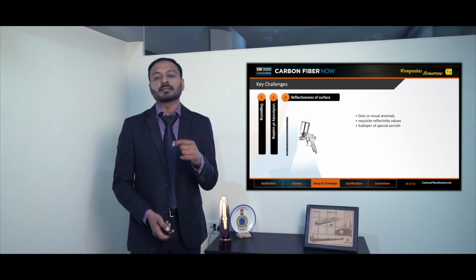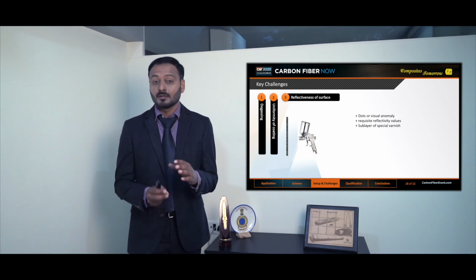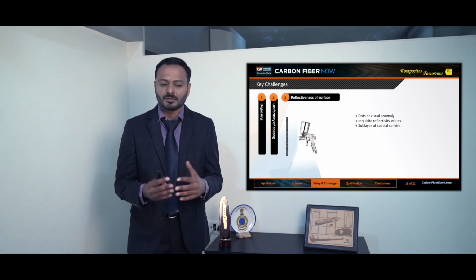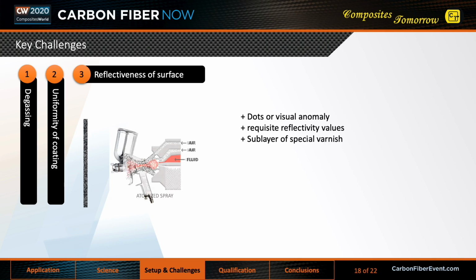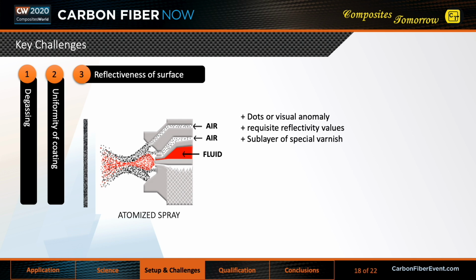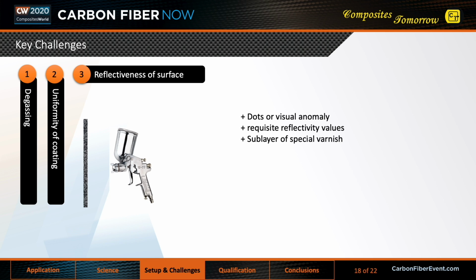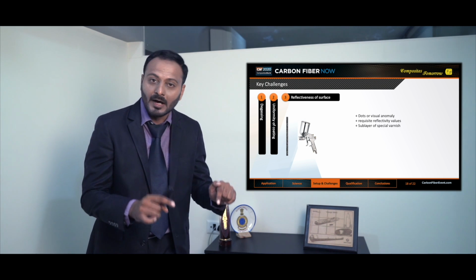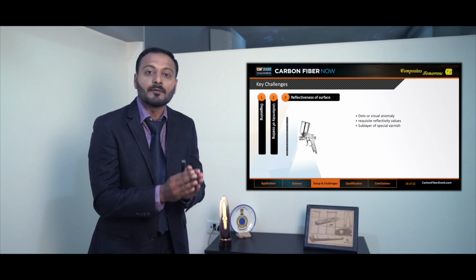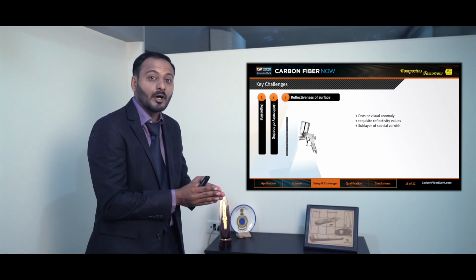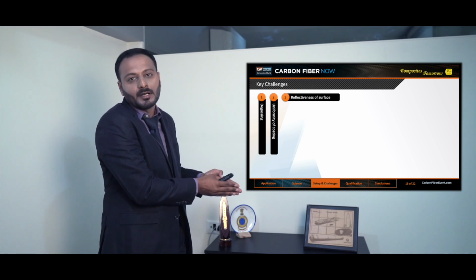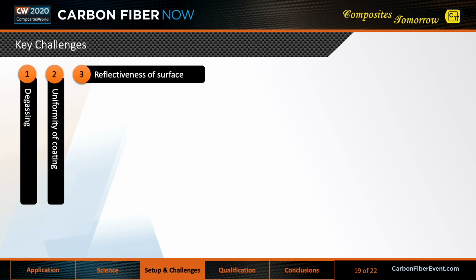Well, a sublayer of varnish, not any varnish, a varnish that can be stable at around 100-110 degrees centigrade, and a varnish that is sprayed by atomizing so that you have a very uniform layer of varnish. The uniformity of varnish is the one that will ensure the uniformity of the outcome of the process of vacuum sputtering. This has to be done in a very zealous manner.